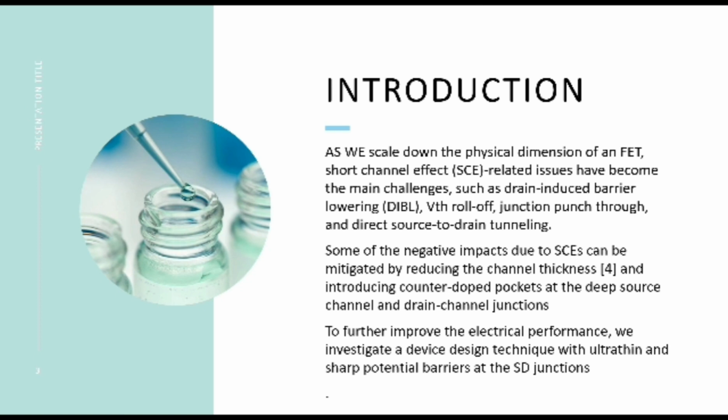This paper further reveals that the tunnel barrier at the source junction dominates the physical mechanism, minimizing the short channel effect of the tunnel barrier FET. And thus, the device performance can be improved appreciably by removing the tunnel barrier at the drain side and by decreasing the tunnel barrier height at the source side. And to further improve the electrical performance, we investigate a device design technique with ultra thin and sharp potential barrier at the source drain junction.